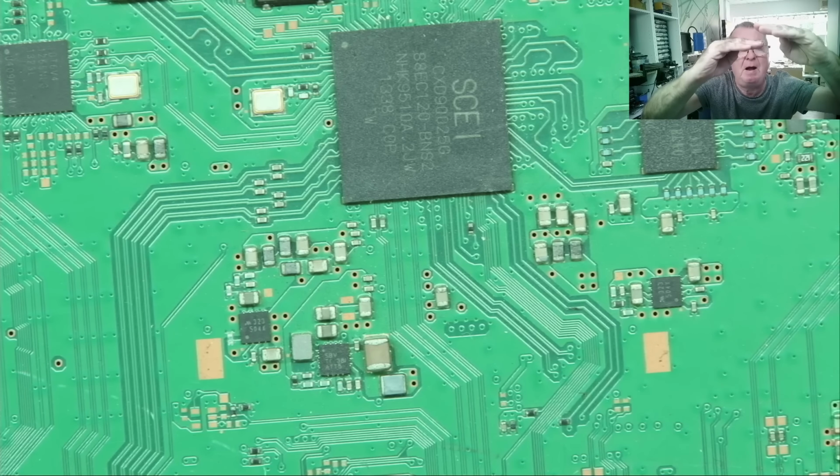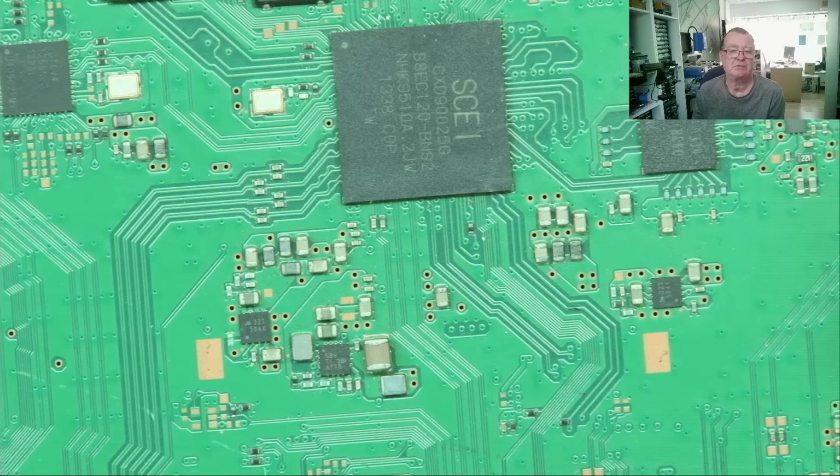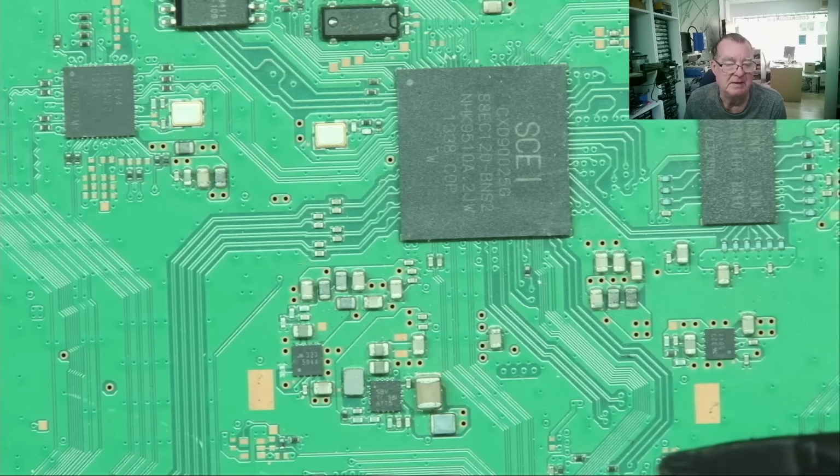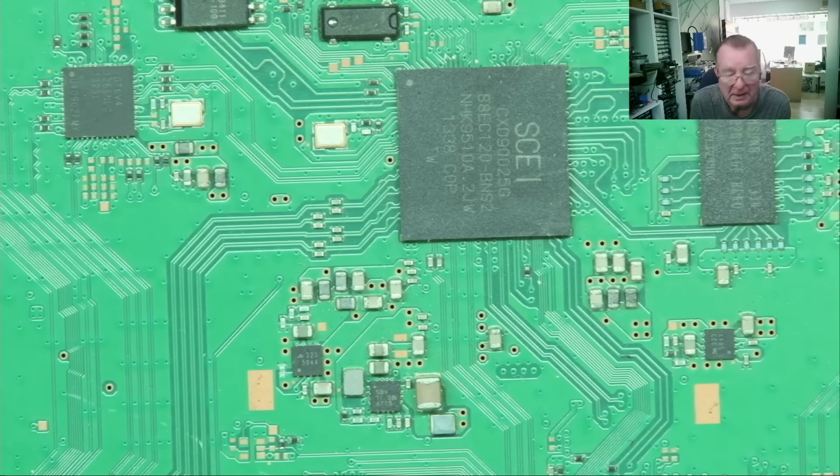Well, what will happen is some of the layers will touch each other, because they're now displaced. And if this layer, which is the negative end of the capacitor, and this layer, which is the positive end, now touch, you have a short. So that's why MLCCs go short when they fail. And I would say always, okay?